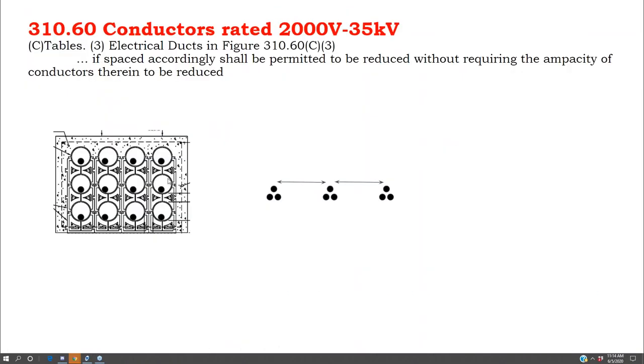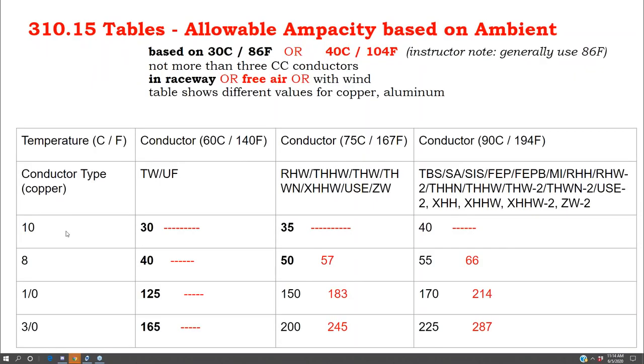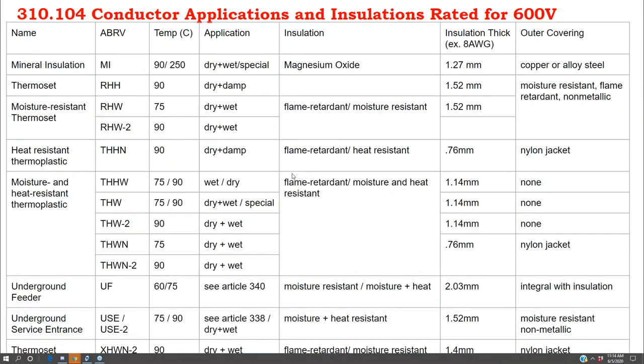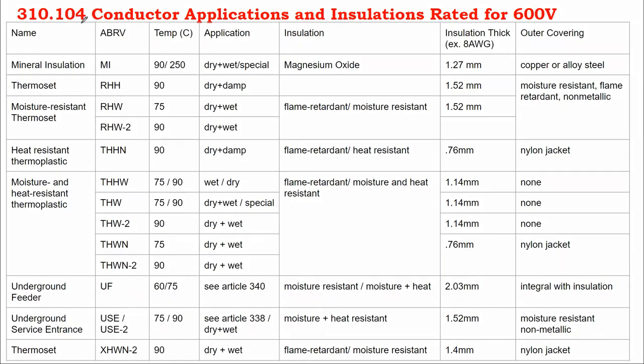Here we go. We talked about this yesterday, about even when you're throwing cables into a trench, you have to space them out in order to avoid them being considered to be bundled together for heat dissipation. Going the wrong way. There we go. So now we get to a section that defines what all of those table wiring acronyms mean.